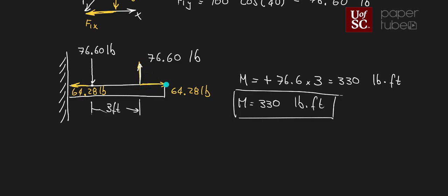Calculate the moment of this force about that point, the moment of the other force about that point, add them together and see what you get. Regardless of the point that you use, you should obtain exactly the same answer. And what that really tells us is that we can take this moment that is created by that couple and apply it anywhere on our rigid body.